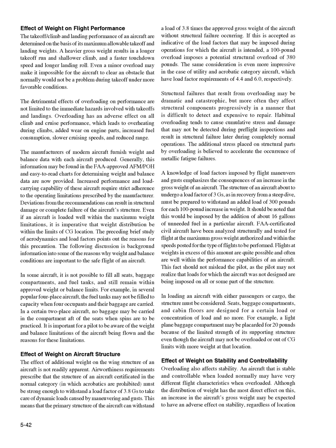The manufacturers of modern aircraft furnish weight and balance data with each aircraft produced. Generally, this information may be found in the FAA-approved AFM/POH, and easy-to-read charts for determining weight and balance data are now provided. Increased performance and load-carrying capability of these aircraft require strict adherence to the operating limitations prescribed by the manufacturer. Deviations from the recommendations can result in structural damage or complete failure of the aircraft's structure.